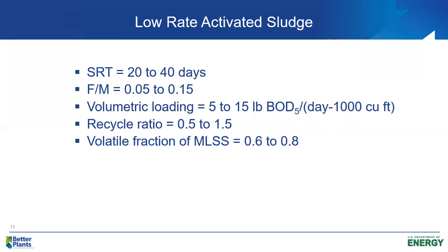They dominate the biomass. Even in a system that nitrifies well, they will be 96 to 98% of the biomass. But even with only 2 to 4% nitrifier population in the biomass, we can do an excellent job of converting the ammonia nitrogen to nitrate nitrogen.